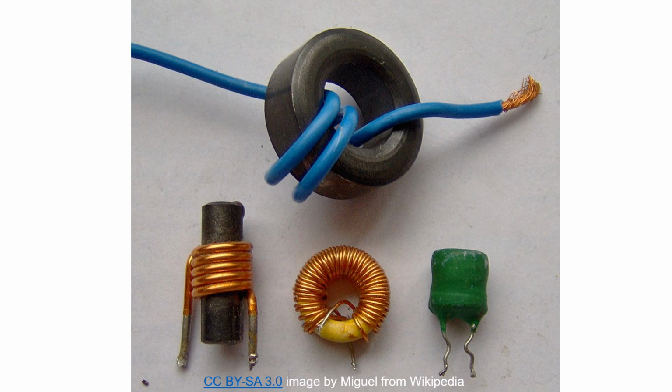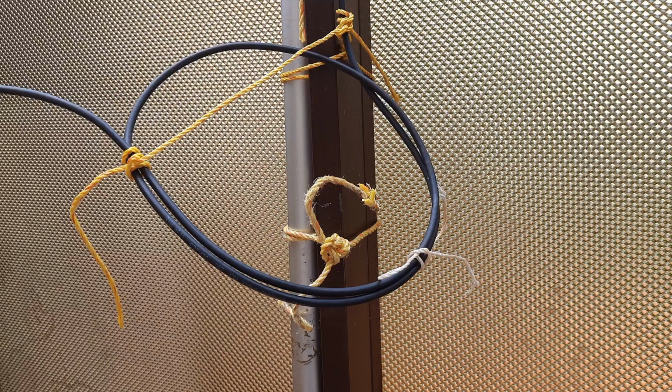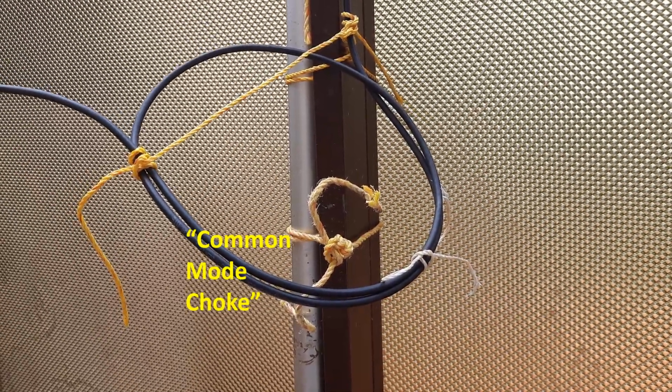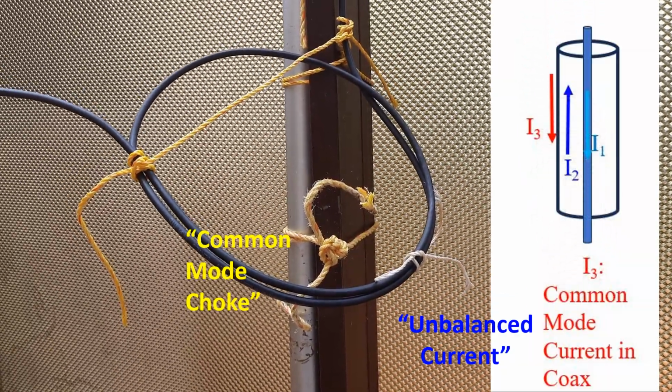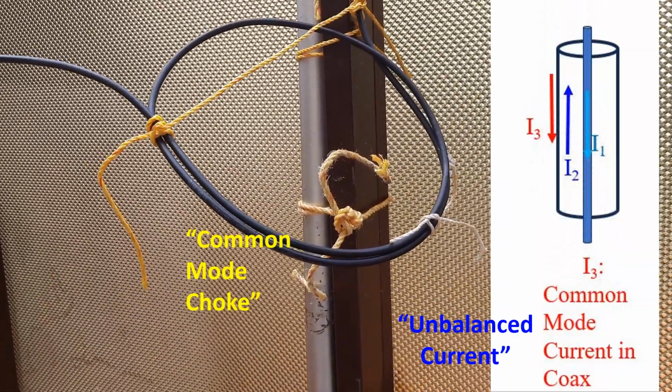But they are not as commonly used as filter capacitors in rectifier circuits, as the inductance needed will make them quite bulky at the low frequency of 50 Hz. At higher frequencies, as the effect is much more, inductors can be used. An important use of an inductor in amateur radio is a common mode choke in feed lines to prevent something known as common mode current, which has been covered in another video on this channel.